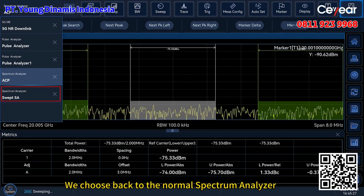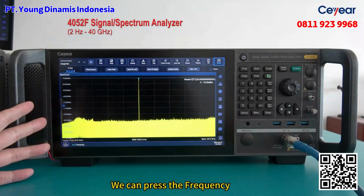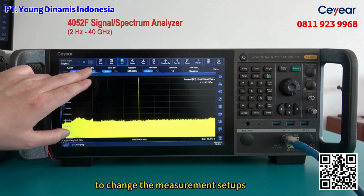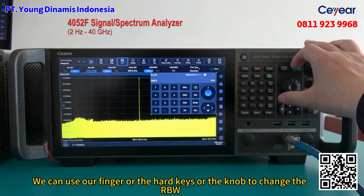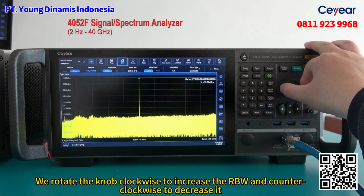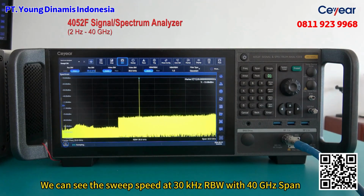We choose to go back to the normal spectrum analyzer. We can press frequency, amplitude, bandwidth on the top to change the measurement setups. Here we can use our finger or the hard keys or the knob to change the RBW. We rotate the knob clockwise to increase the RBW and counterclockwise to decrease it. We can see the sweep speed at 30 kHz RBW with 40 GHz span.